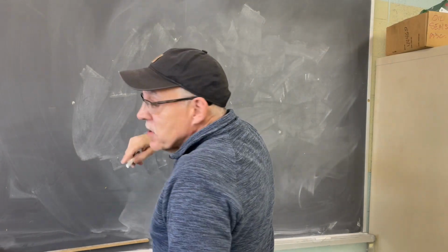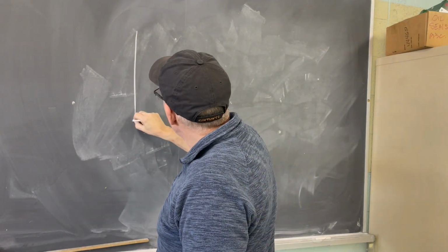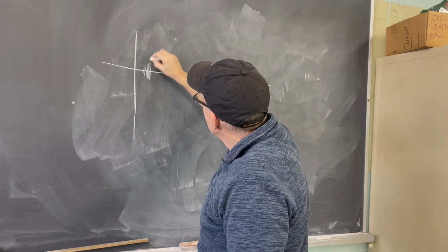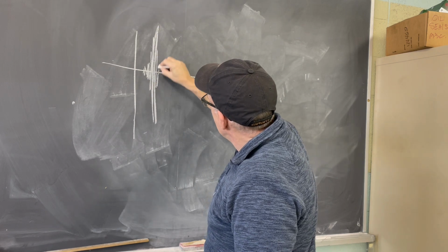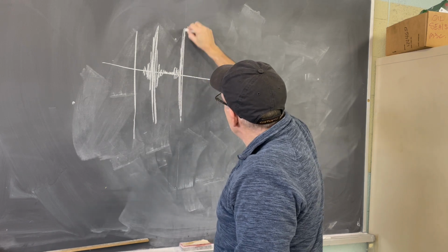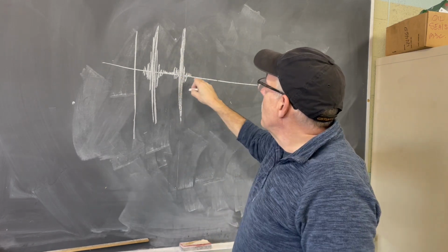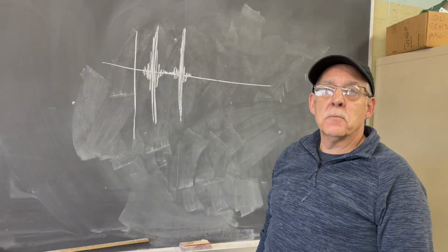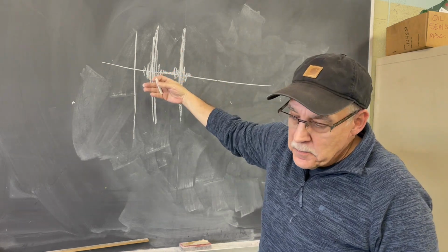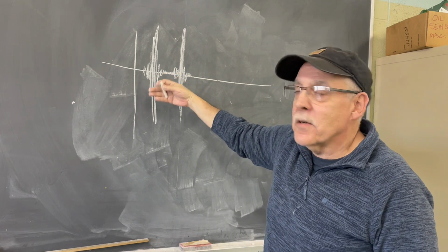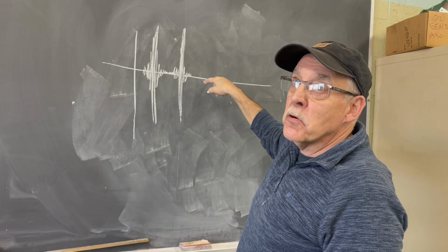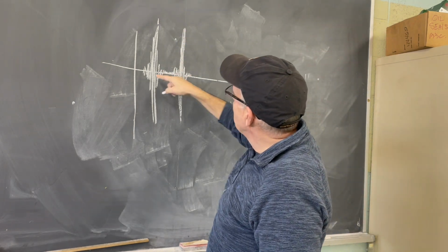Okay, so certain waveforms can tell us certain things, these complex waveforms. So for instance, if I had a waveform that went like this, come down like that. Something like if we had a missing gear tooth or something like that, this has all the vibration from that gear in it, has all the vibration from the bearings in it, has all the vibration from everything in that piece of equipment we took a reading on. So we have a complex waveform. But if I had a broken gear tooth, I measured the time between, we call these impacts.